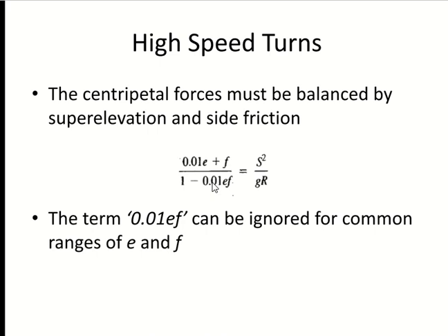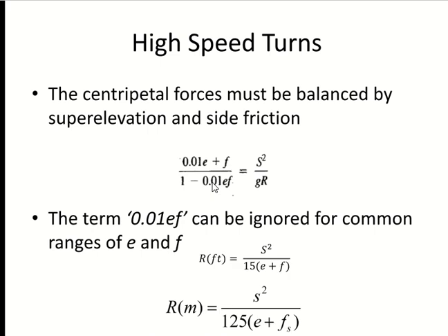I'll finish it fast, only 2 slides here. When you are making a turn at high speed, you have to balance the extra forces acting on the vehicle, the external forces, with the radius and super elevation. What is super elevation? The tilting of the road, the cross slope of the road. So you will control the external forces with the cross slope and with the radius.